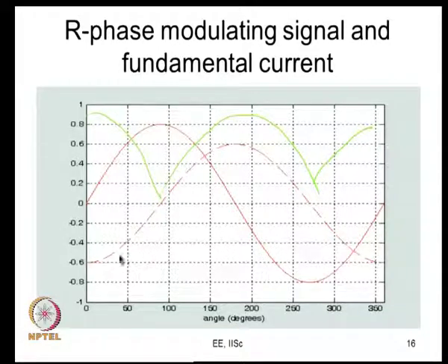If we are looking at sinusoidal PWM, first we are looking at sine triangle PWM. So, there is load. Now, the average value depends on what? It certainly depends on this peak value. What does this peak energy loss depend on? It depends on the peak current. So, if the peak current goes up, then this will also go up, its average value will go up. So, the switching energy loss certainly depends on the peak value of load current. That is very clear, it is just common sense. But it does not depend on the modulation index. That is a very interesting aspect.